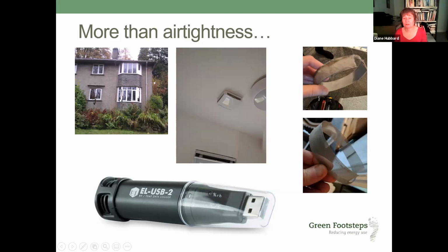It's suspended floors, quite a lot of widespread issues. The bays on the front are just timber frame, slate hung. There was loads coming in through there. Post refurb, it came out about 4.5, I think, in terms of air permeability.